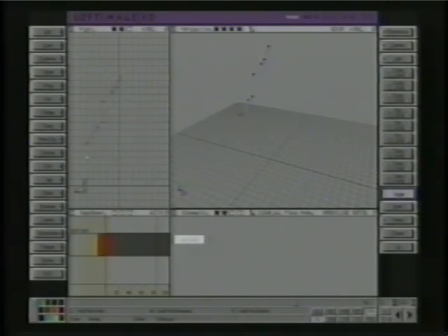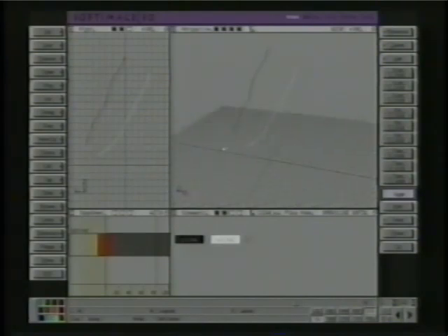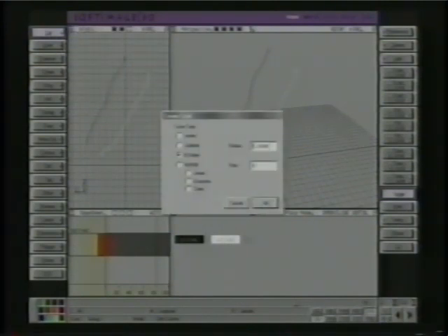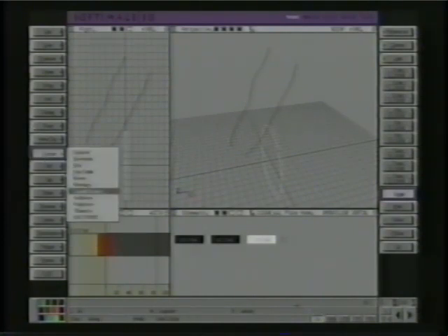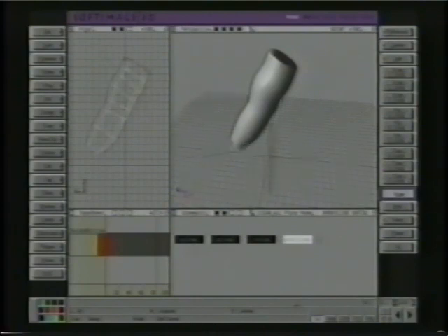So let's say we want to do an arm of some sort. Okay. So we draw one profile and then duplicate it and modify that to be the other profile, or we could have just drawn a new one with the same amount of points. What we're doing is creating two rails for the circle here to extrude up, and you get a circle, and it needs to be B-spline, not NURBS, and then rotate it. Oh no, this one you leave unrotated, excuse me, and you leave it just like it is when it comes in. Then you go to Surface, Guided Extrude, Scale Width and Height, select the cross section, the left guide, and the right guide, and you can follow the prompts down in the command output there.